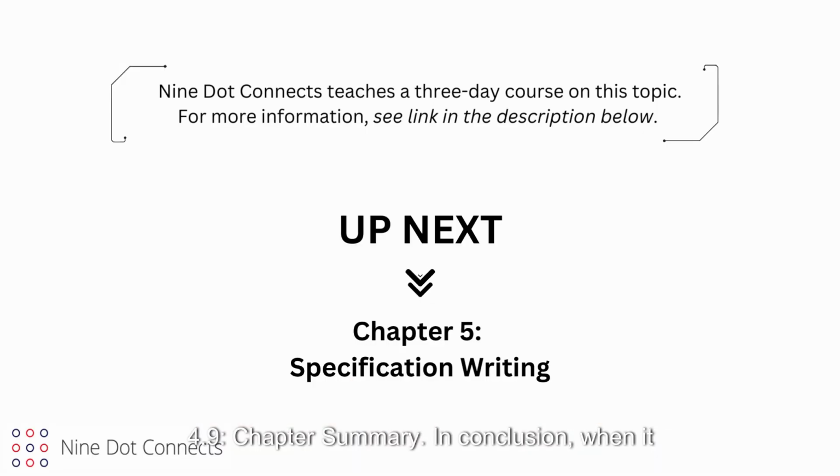4.9. Chapter Summary. In conclusion, when it comes to test, the assembly and fabrication houses can only work with what was given to them. It is important to know what equipment they may have, what files may be of use to them, and if any JTAG configurations have been designed into the PCB. Even if the design test does not opt for assembly test beyond basic continuity checks, assume that the board will need to be tested by the design team, and that issues will arise.